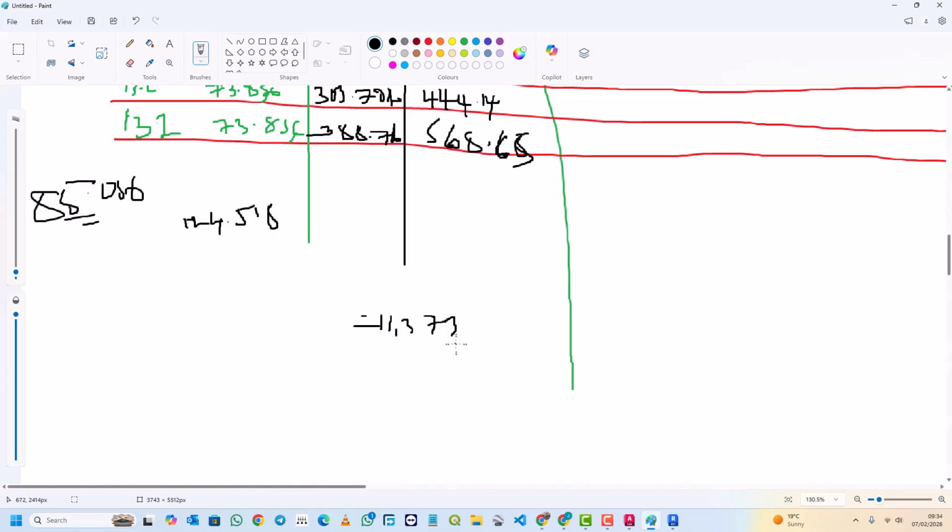Then this area, you square root it if you want the square footing. So I'll just square root it. Why do we divide it by 50? 50 is for preliminary design, that is from the experts' point of view. If you divide by 50, you'll get the size of the column that will be suitable enough to carry your loads.